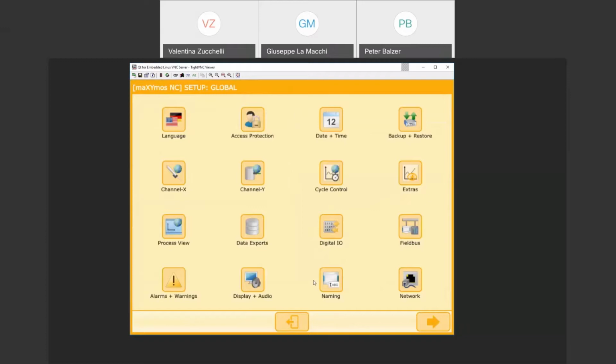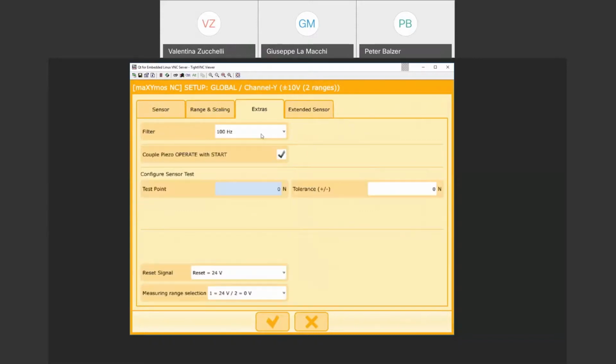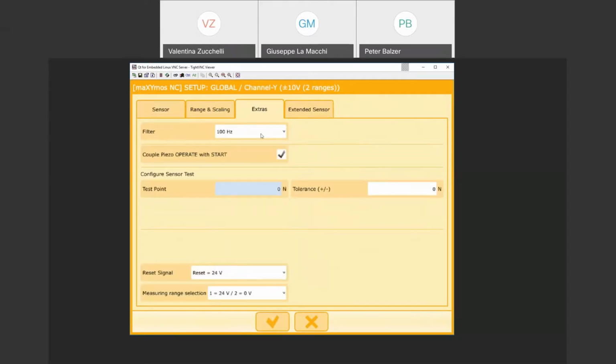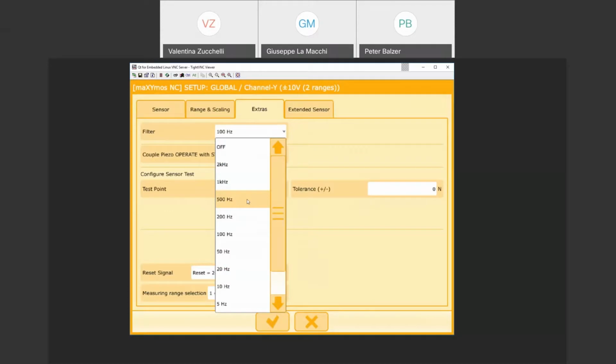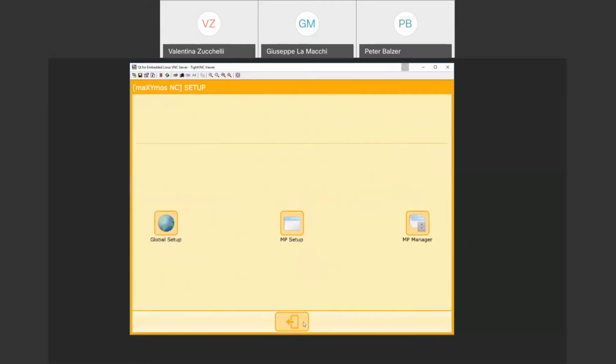And the second one, if you have a really high sampling rate, all these evaluation objects regarding gradient change are quite sensitive. So what I would also like to activate every time when I'm using one of these evaluation objects is a low pass filter. If you're working with 10 kilohertz, you have some small peaks inside of the force and displacement curve. Everything will be detected as a gradient change. So please, you don't need to go down to 100 hertz, but at least you should use 500 hertz, just to avoid some small peaks which accidentally can be marked as an inflection point or something.